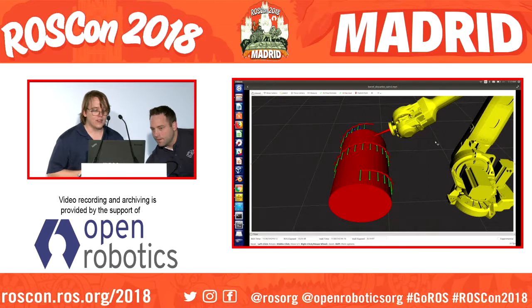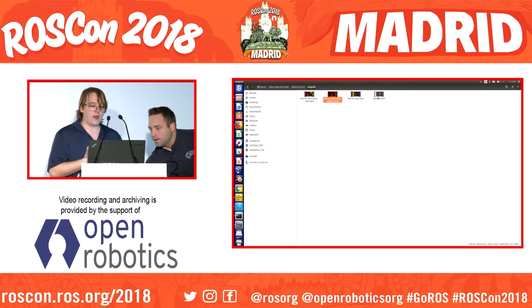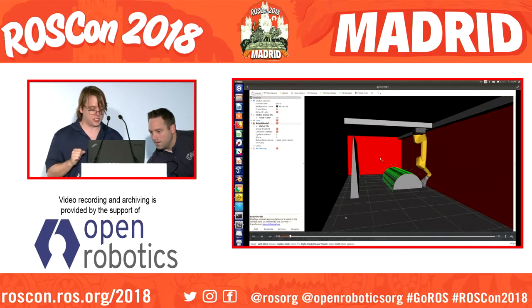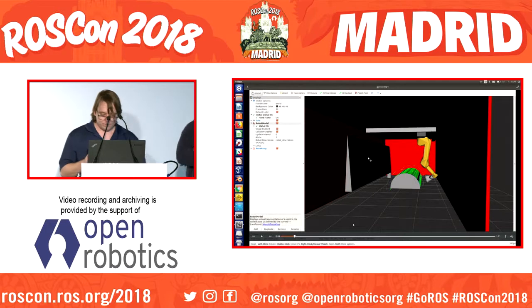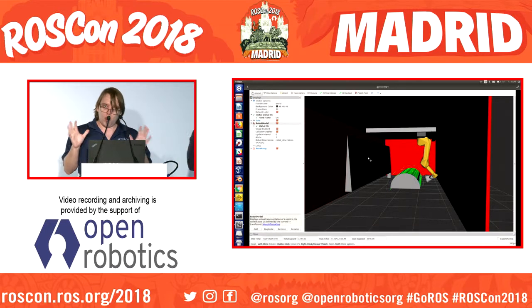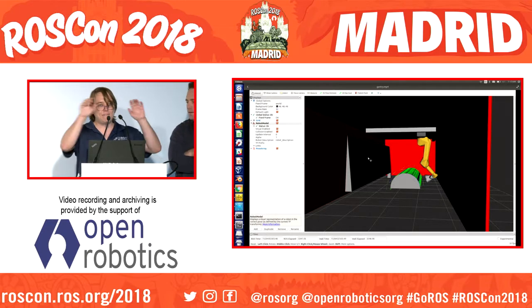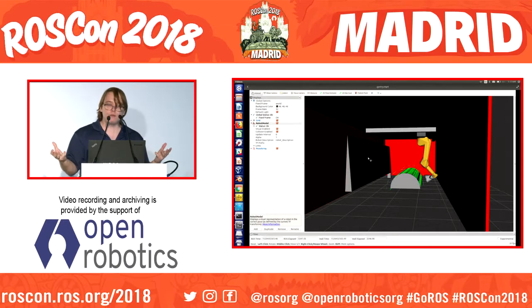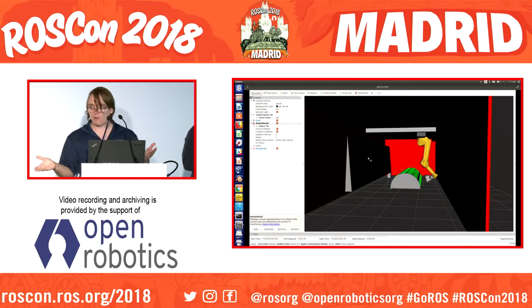So last but not least, I want to talk about something some people will extend this conversation with, which I'm really excited about. This is one other really cool thing that sampling to TrajOpt lets us do. Imagine you didn't have just one path that you were trying to do, but many paths together. Say a lot of welds on a part, or many rasters when you're painting something with a robot, right?